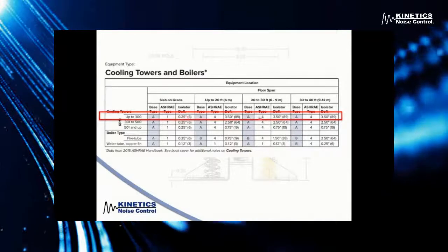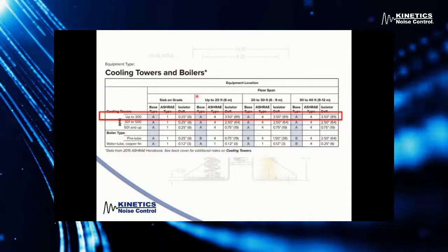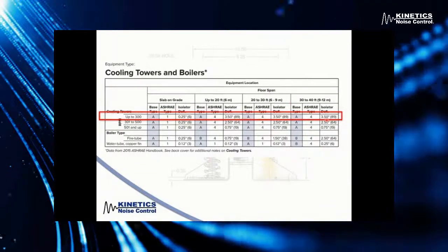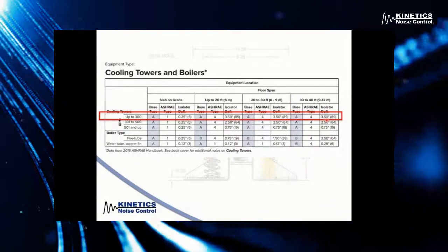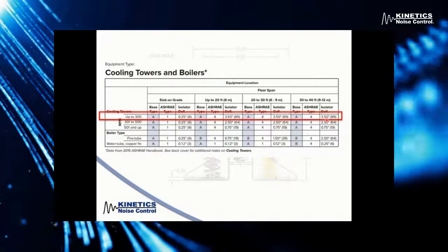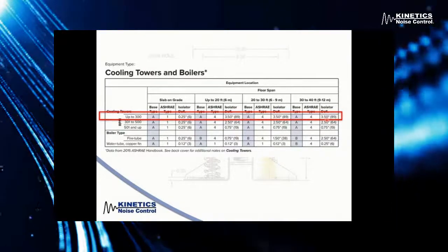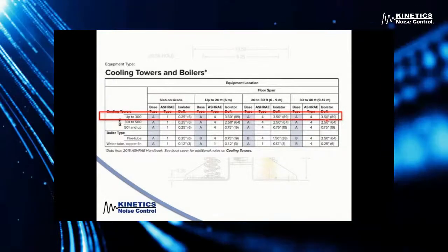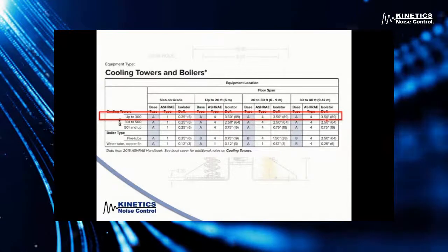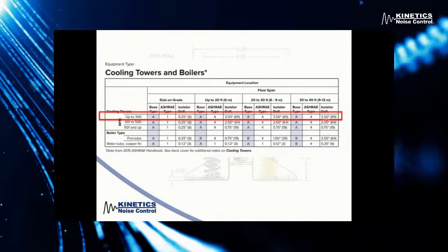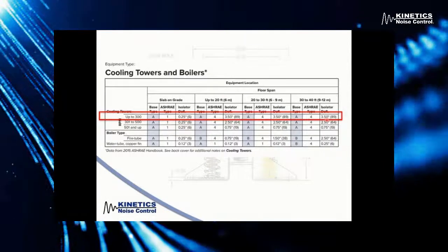We go to the very far right of this scale. In other words, as the floor span of the building widens, which typically happens the higher we go in the building, the supporting beams for the floor are wider, and you get a wider floor span. What happens is that once you get a wider floor span, the floor itself actually starts deflecting between its supporting columns.